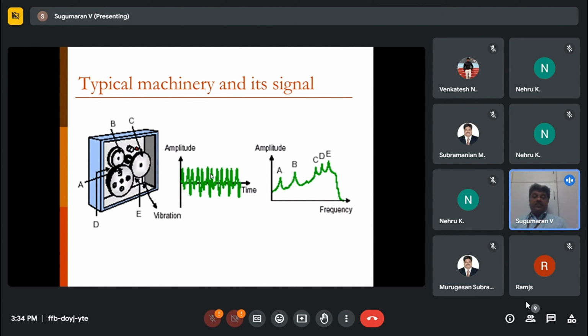Okay. So earlier, people did fault diagnosis using the spectrum. Whenever we say spectrum, it is frequency versus amplitude, so it's just spectrum. They just use the spectrum and identify that there is an increase in amplitude at this particular frequency, and from that they infer that A corresponds to this big gear. That means there is some problem in that particular gear.